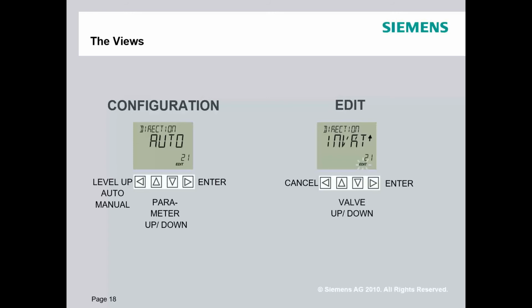Okay. Thanks, Wes. One more question popped up, and that is, can natural gas be used for the supply pressure? Okay. This positioner right now, the PS100, no. Because in the PS2, our flagship product, we use it on gas pipelines every day. Because it's a no-bleed positioner, the EPA likes it. The gas people like it because I don't blow their product in the air.